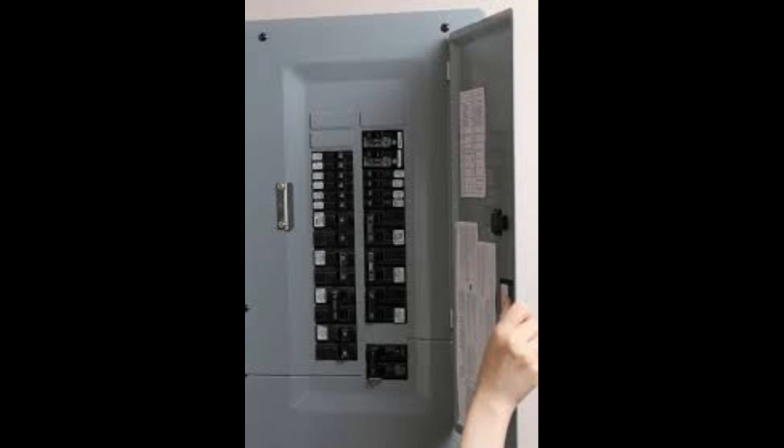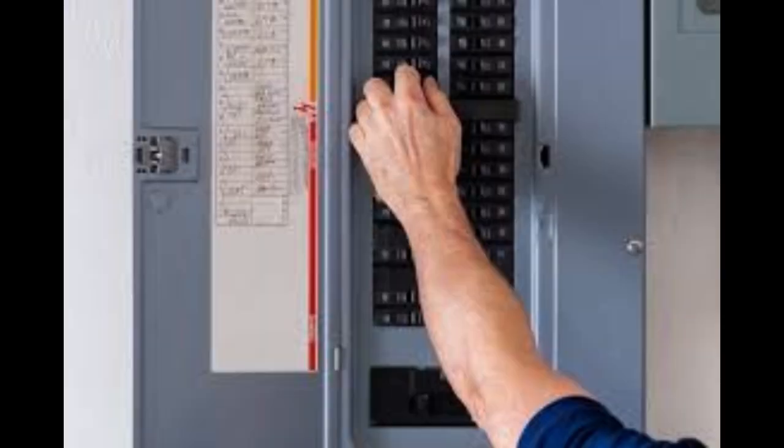B. The absence of or deficiencies in the grounding electrode system. C. Missing or damaged dead fronts or cover plates. D. Conductors not protected from the edges of electrical cabinets, gutters, or cutout boxes. E. Electrical cabinets and panel boards not appropriate for their location, such as a clothes closet, bathrooms, or where they are exposed to physical damage.